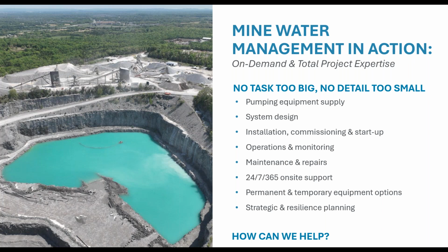Well, that's a great question. And yeah, there's certainly a few ideas that come to mind. If your pumps are clogging, then you're likely running at full speed with little or no flow. If it's a submersible pump, then typically you're relying on pumped water to help cool the motor. So without that flow of water, your motor windings could be overheating to the point of failure.